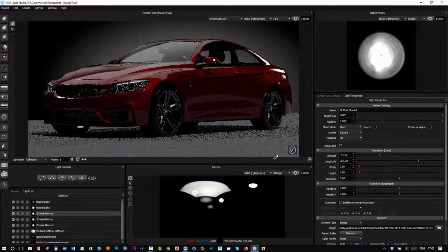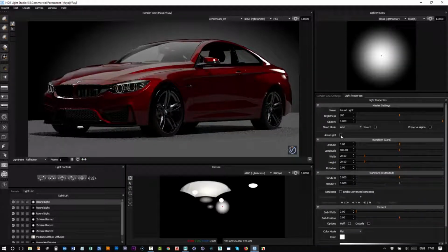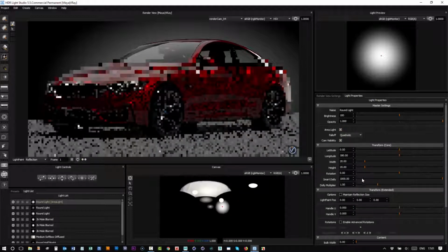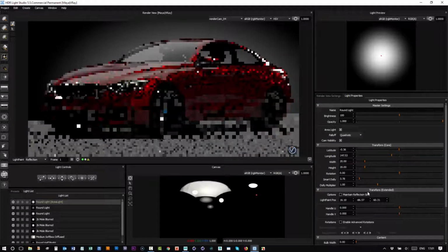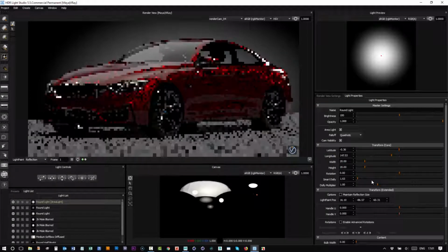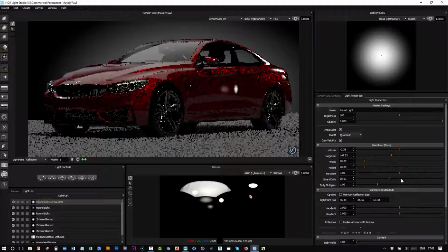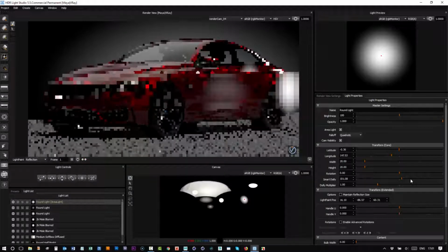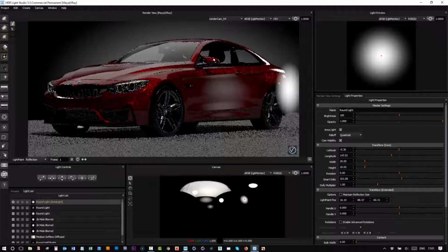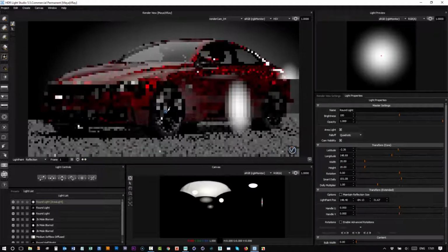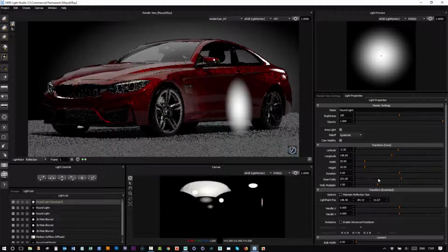And of course, any light that you make in HDR LightStudio can be promoted to an area light. So if I say make a new light, make an area light, and then dolly that into the model, and say we click on here, you can see that 3D light source has been made in Maya and V-Ray. So if I want to light up this wheel here, click in the middle of the wheel, and then I'll dolly that in.